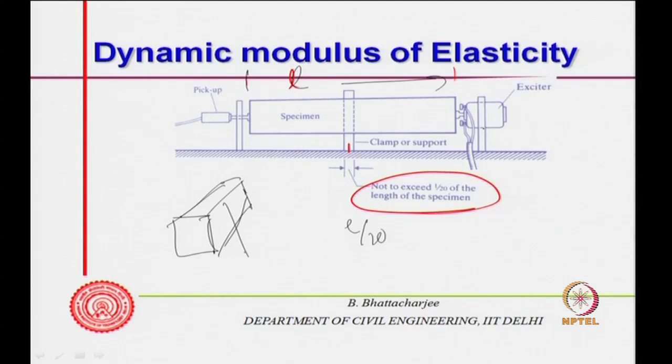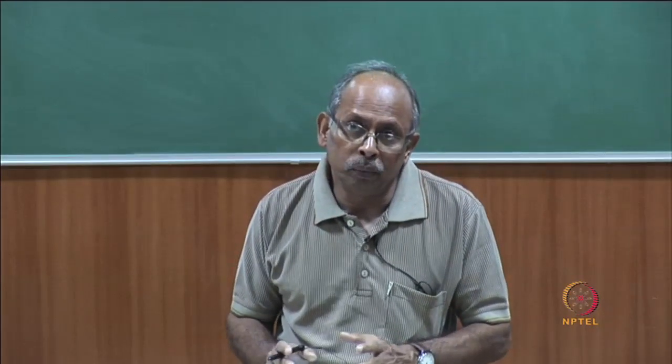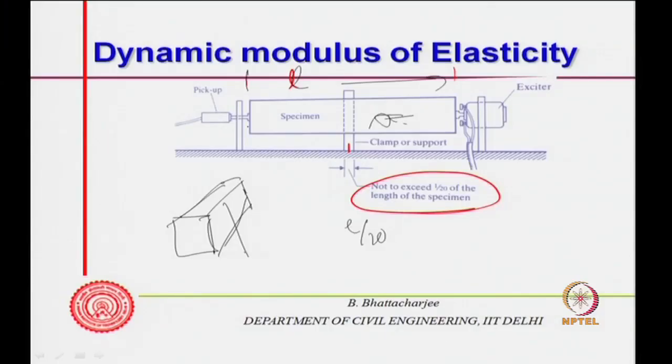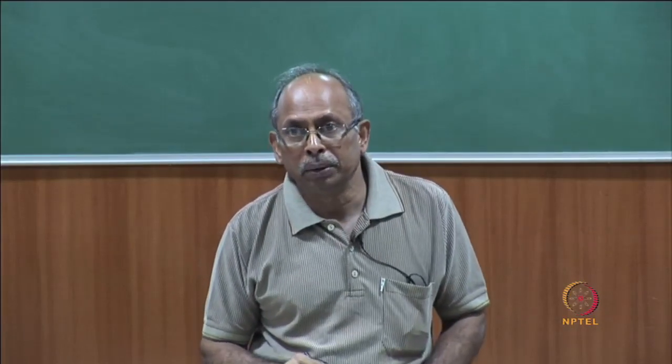The exciter imparts acoustic pulses, or acoustic waves, basically. So, a longitudinal wave will be travelling along this direction, and here there is a pickup which will pick up the pulse transmission, the signal that is transmitted through it.